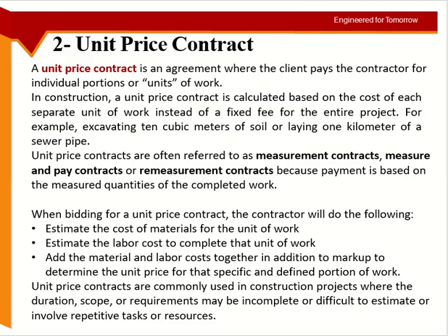So everything which we said for the lump sum contract, the total price, everything which he was adding in the total price, he still adds. But now he will distribute it in each work separately. So he may say, I will just take 2% overheads for excavation. But for concreting, because I will be hiring the mixer and everything, I will add more profit on that activity. So this can be done as well.